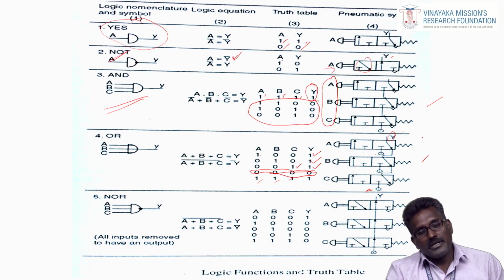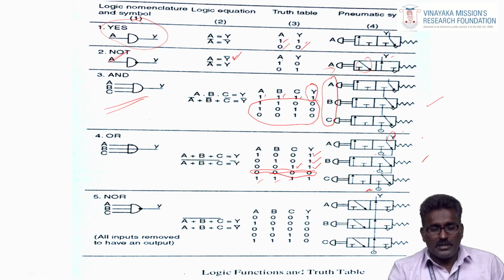If they watch any adverse situation arising, the security person is able to stop the boiler from his location. So these three switches are placed in separate positions: one in the control room, one near the boiler, and another with security. If anyone finds anything going wrong, anyone can stop the system.